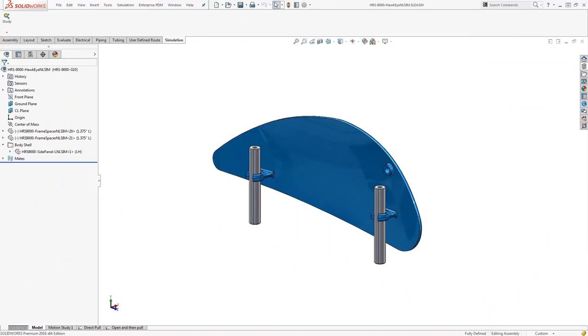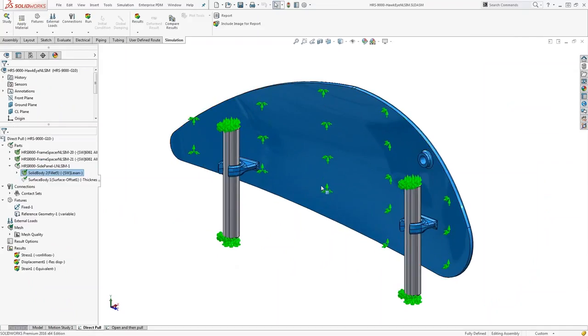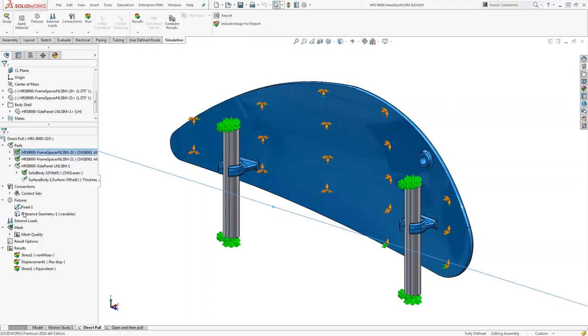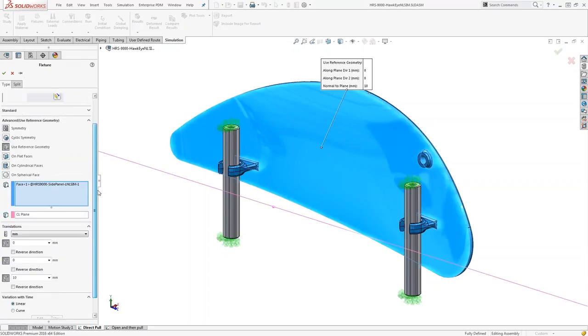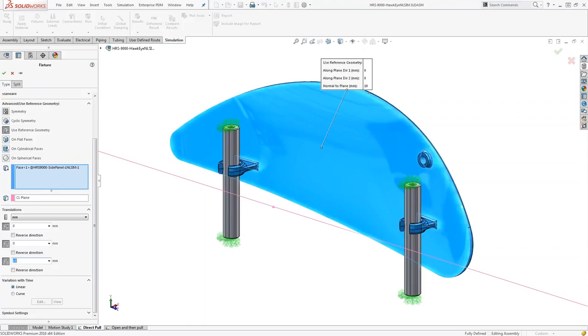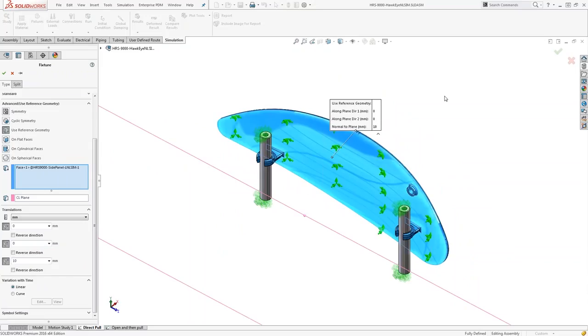I'm sure there are more, but let's look at one way. That's a direct pull kind of method where we're taking this piece, and all there is to it, if I look at the setup here and edit this definition, is a displacement in the x-axis of about 10 millimeters. So we're taking this plate and moving it out in the x direction, 10 millimeters.